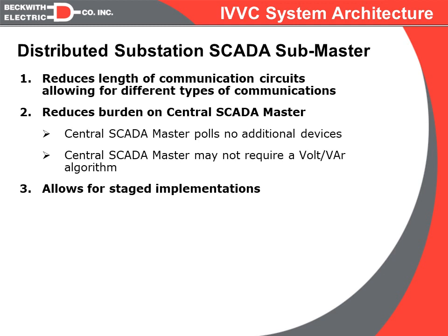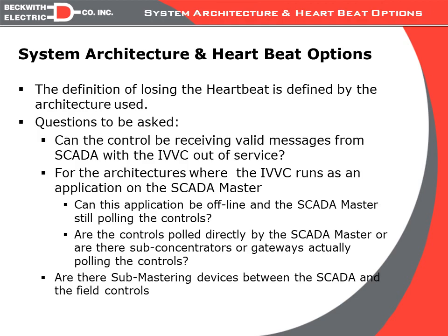It also helps in that instead of having one large system to implement, we can now implement in smaller chunks or in phases. We can take one substation at a time, apply the amount of capacitor banks we need, have all that communicated back to the substation, and then we're going to allow the substation to do the IVVC algorithms.